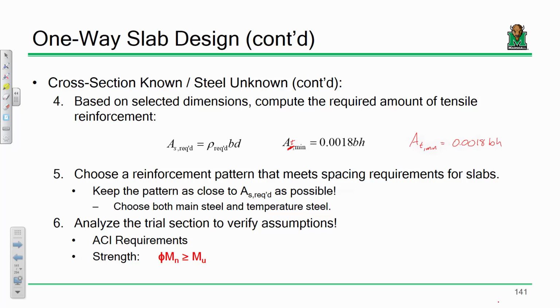All right. Well, with slabs, when you're designing a slab, you have reinforcement going this way, but you also have reinforcement going the other way. One direction is to actually resist the load, to actually hold up the slab and make sure that it can support whatever load is on it. That's what the A_s is. The A_T is what's called temperature reinforcement.